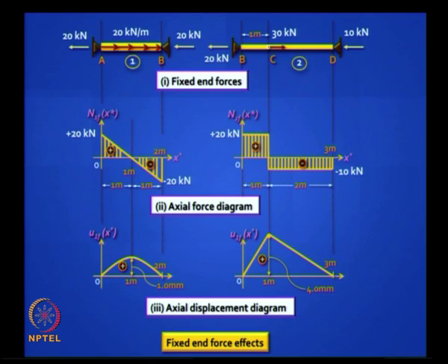So I am not going to repeat this part, it is well known, but here we have this problem that I talked about, the problem of how to handle this situation. Well, you can't handle it if you have only 1 degree of freedom per element. So you forget about how to handle it in a mathematical framework, just put it all together manually and tell me what F1 and F2 and F3 are going to be. What are the equivalent joint loads due to the intermediate loading? Can you tell me what F1F is?